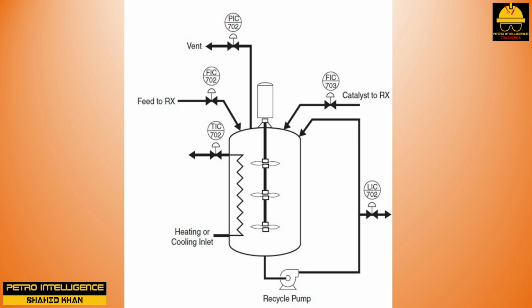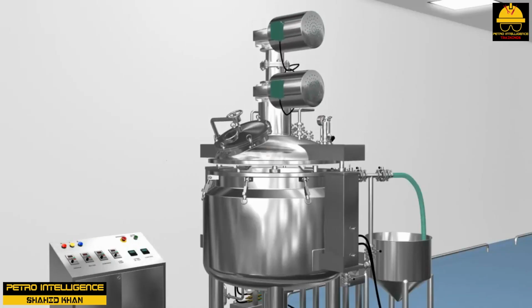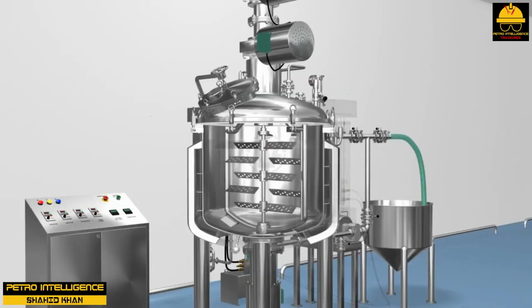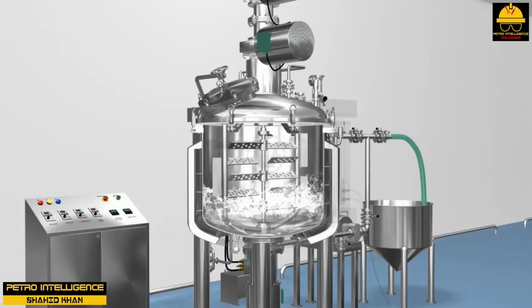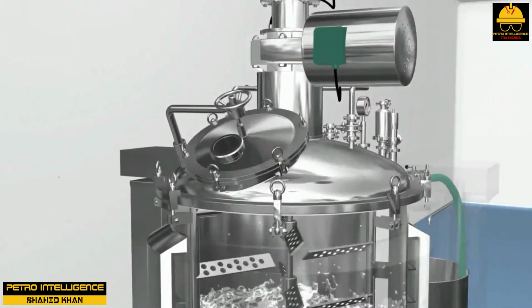The automatic shutdown allows a technician to push one button and shut the unit down in the event of an emergency or runaway reaction. A stirred tank reactor is often referred to as an autoclave or batch reactor. This type of reactor is used in both batch processes, such as the suspension vinyl resins unit and the phenolic resins unit, and continuous feed processes, such as the solvent vinyl resins unit and the polyethylene unit.